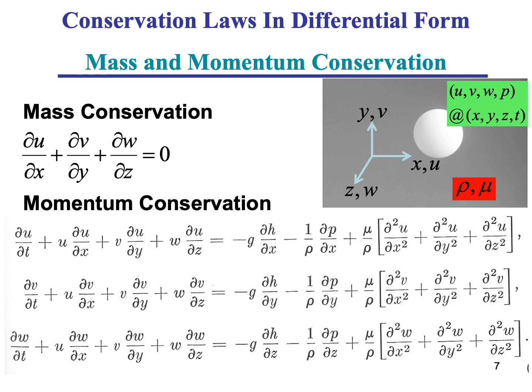So moving on. The equations of motion that we are going to be dealing with are mass conservation, so mass is not created or destroyed, and momentum conservation, which is Newton's second law. Summation of external forces will be equal to the rate of change of momentum as well as the net fluxes of momentum. So now let's define terms. So we defined a domain. This was in the previous slide, we defined this as our domain, which actually contains our fluid of density rho and viscosity mu.